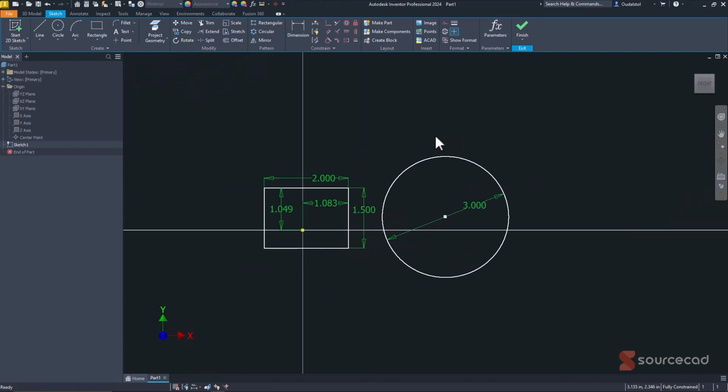And so there are times, so let's back up a little bit. If I don't want this padlock here, I can click that and delete it. Or if you kind of wonder, what constraints do I have? You can click the F8 button, and the symbols will show up. And like I said, these yellow dots indicate what you have as the coincident one. But there you can see the padlock. I can click it, I can delete it, and I'm back.